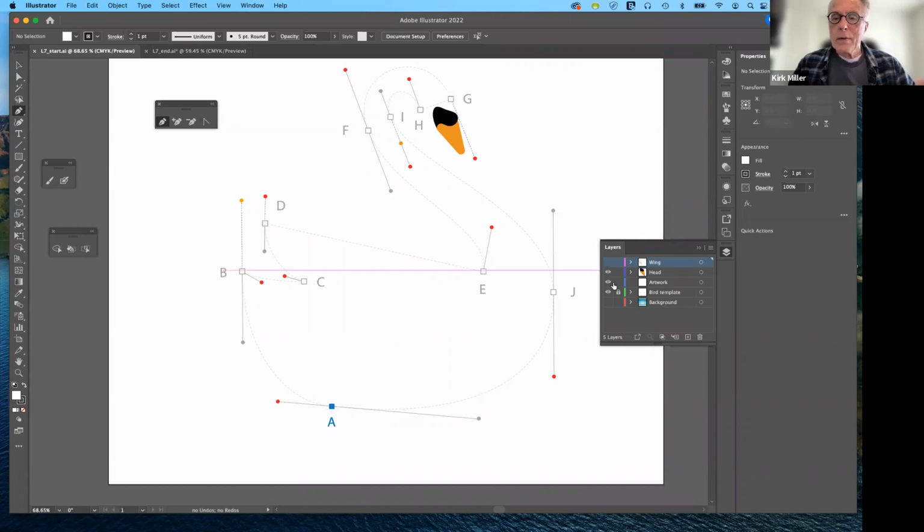the correct layer selected, which is artwork. Make sure that it's visible, that it's not locked. Okay. And with the pen tool, if you have another layer selected that is locked, you're going to get that little symbol with a pencil with a little crossed out circle on it. That means you can't draw on that. So that's kind of a quick indication that you need to look at layers and make the necessary changes here.